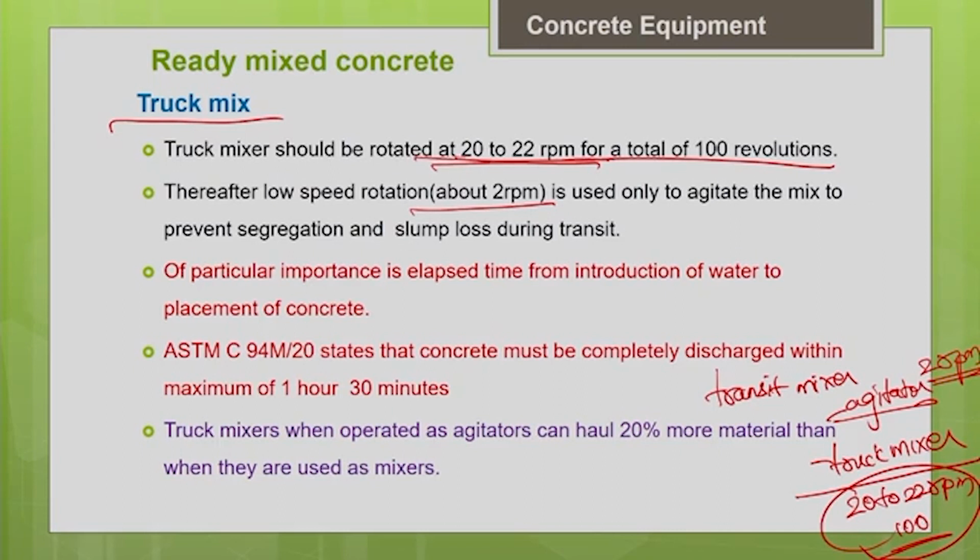So, generally when you use a transit mixer as an agitator, I can use more capacity of the truck than when I use it for preparing the concrete. Okay. So, important thing to be noted is the elapsed time from the introduction of the water to the concrete to the placement of concrete. That is very important with respect to concrete. The time is very critical, because as I told you, once you add the water, the cement starts hydrating, it starts stiffening, the setting will start. Okay. So, that is why there will be loss in workability during the transit.